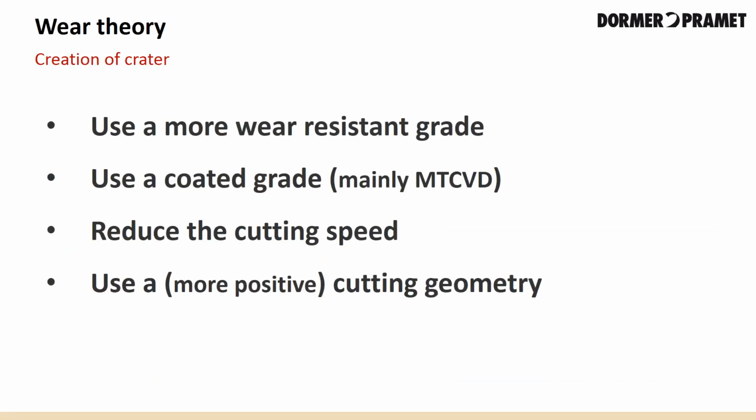So again, the question arises, how can this effect be minimized or slowed down? We can use a more wear-resistant grade. We can use a coated grade, MTCVD, reduce the cutting speed, or we can use a more positive cutting geometry.